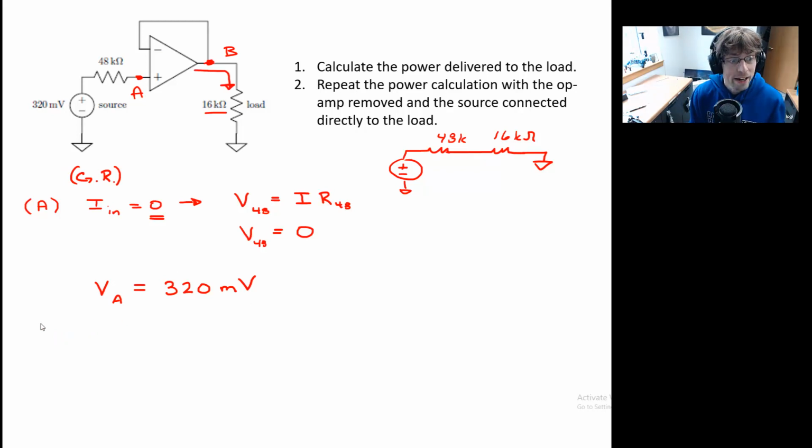So let's go ahead now and take a stab at node B as in boy. And keep in mind your golden rules for operational amplifiers. What's VB going to be equal to? Yeah, you got it? Remember, one of our golden rules tells us that the potential of the inverting input should equal the potential of the non-inverting input.